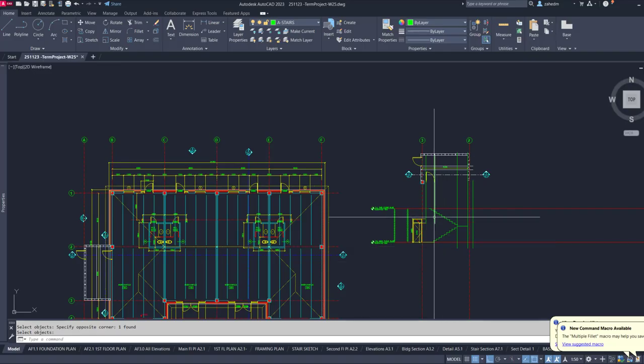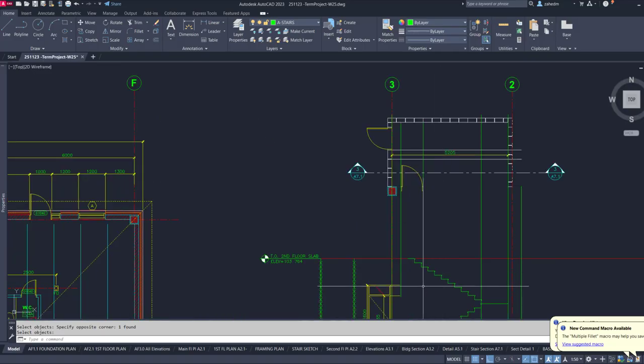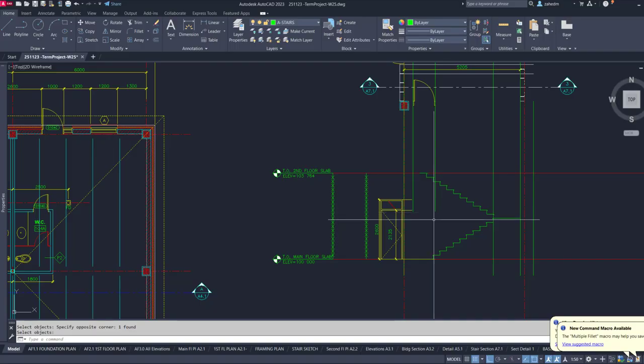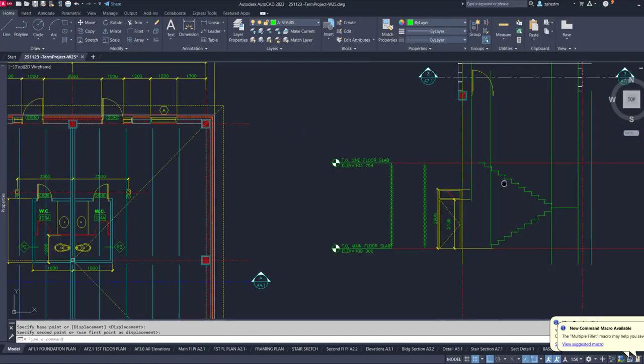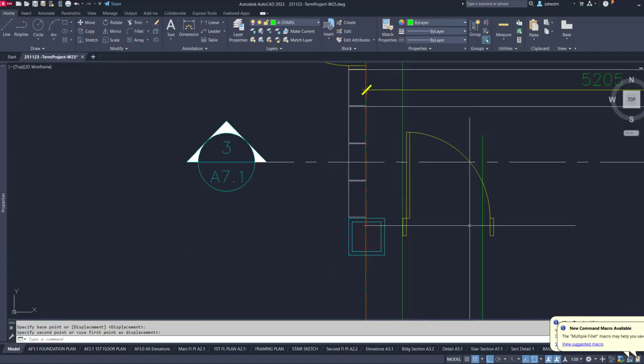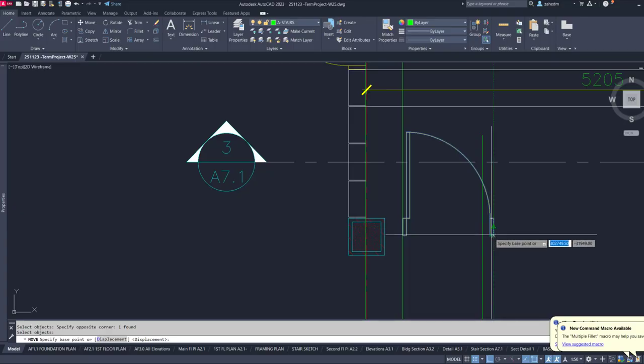So the stairs should be designed at this point. How it's going to be, I'm going to move this and put it right at the nosing here. This nosing shows that in this corner, this door is going to kick the step, which is no good. So I have to basically move it to bring it to an exact corner.